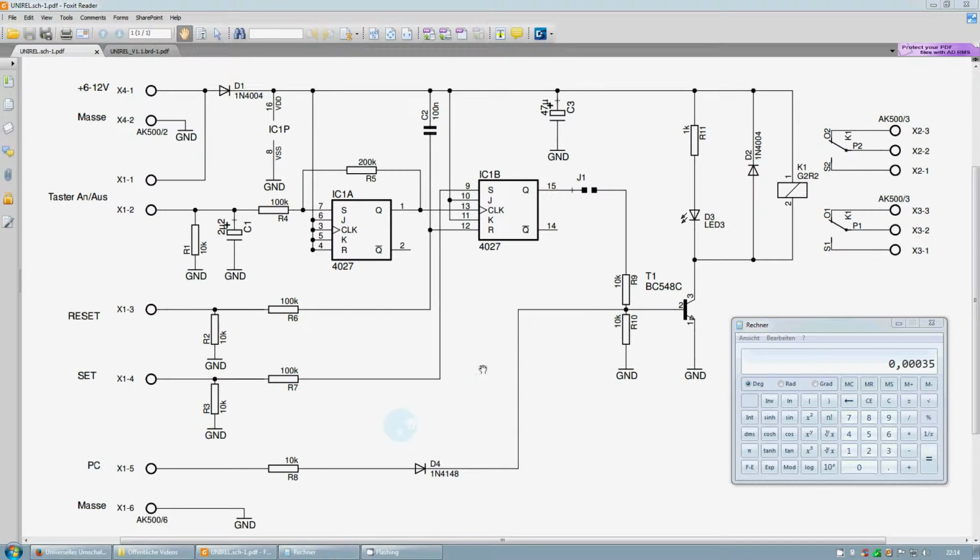So we saw that we need at least 350 microamps base current to switch the switching transistor on. Now these 350 microamps are also flowing through this diode, and they must flow through R8. Now the question is, what voltage do we need to have a current of 350 microamps flowing through R8 so that we have enough base current?